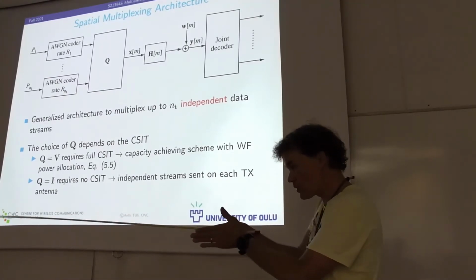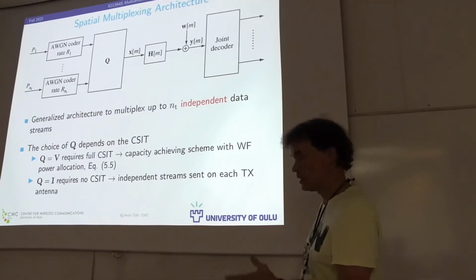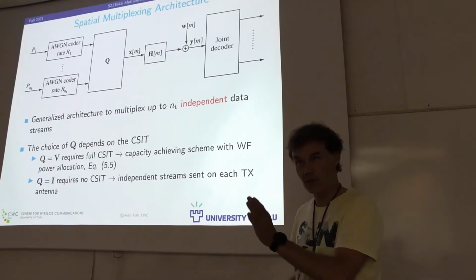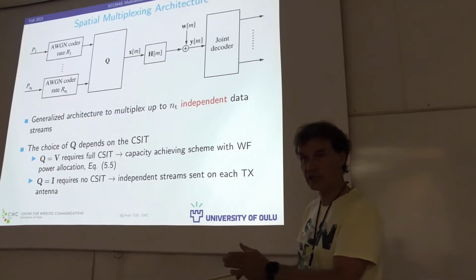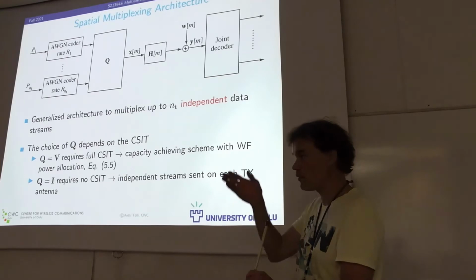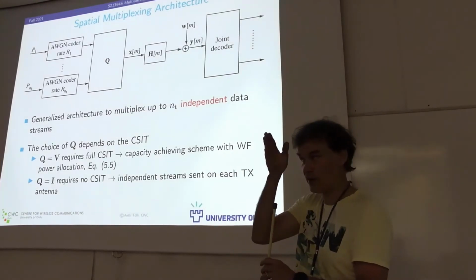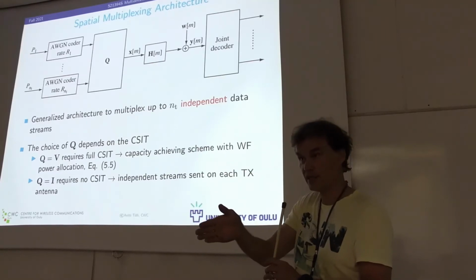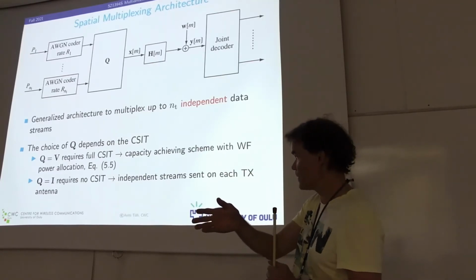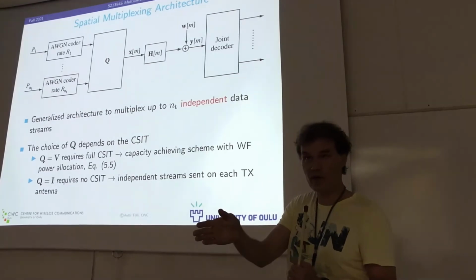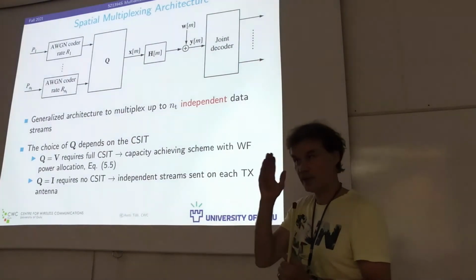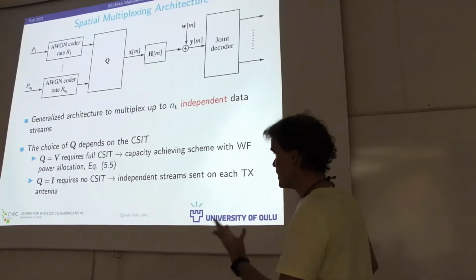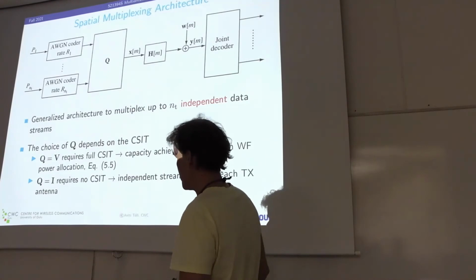With narrow angular spread, like line of sight scenarios, the statistical properties of uplink and downlink are more or less the same, so you can use the statistical channel knowledge. For example, if you have a line of sight channel, you have no fading and the channel becomes deterministic. Acquiring the channel is basically estimating the angle of arrival in uplink, and then using that information for the downlink transmission. Basically, single stream beamforming.